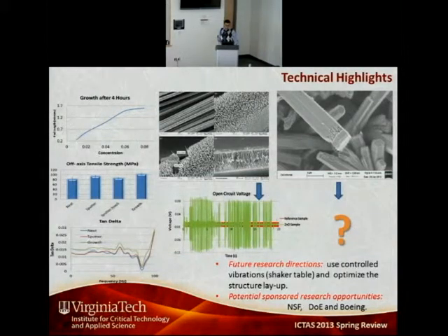So our explanation here is that the adhesion between the nanowires and the epoxy is good. And then we believe that the interaction between the nanowires, from the opposite faces, and the epoxy is much better than the properties of the carbon fiber itself with epoxy. So that's why here we get better results in the off-axis.